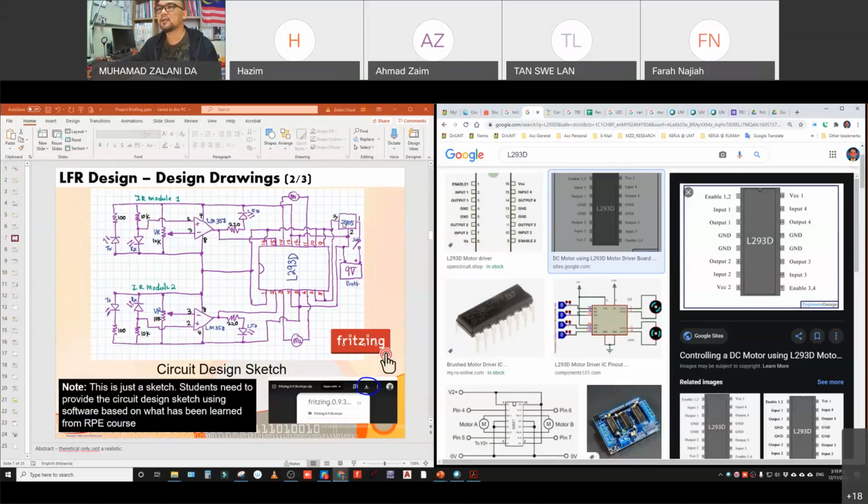Make sure that when you connect the 5-volt supply from the 7805, we have 5 volts of supply. We will supply it to this IC. So make sure that the connection of 5 volts is to the right pin. This chip, this IC, will use 5 volts. Then it has the corresponding groundings as well. Make sure that the grounding is connected to the ground.